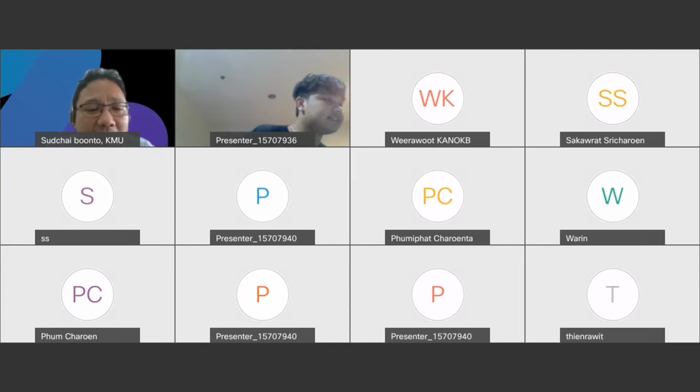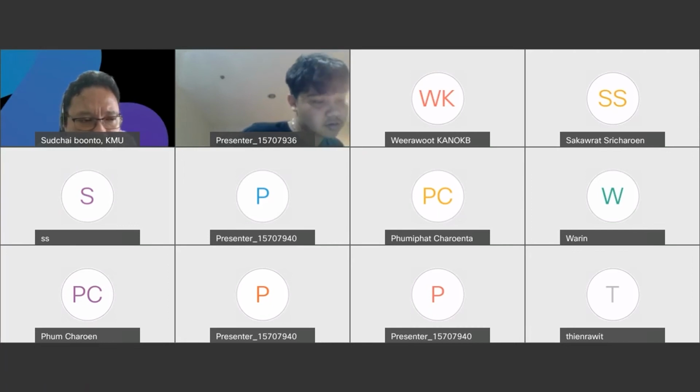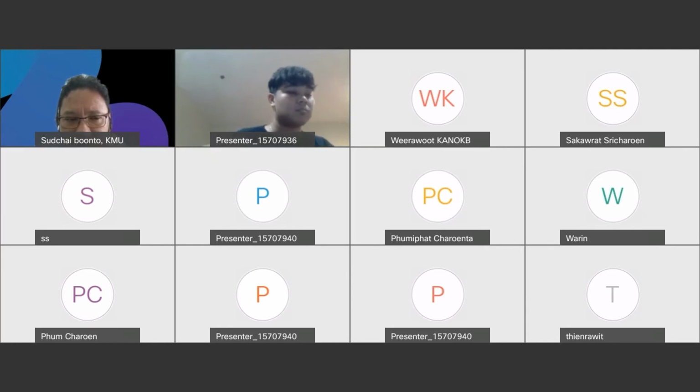I selected the bandpass filter from the reference research. I referenced other research and applied it to this work. But if you select the notch filter in between the bandpass range, does it not disturb some data that you want to use at 50 Hz? Because the notch filter will cancel out the signal at that frequency, right?